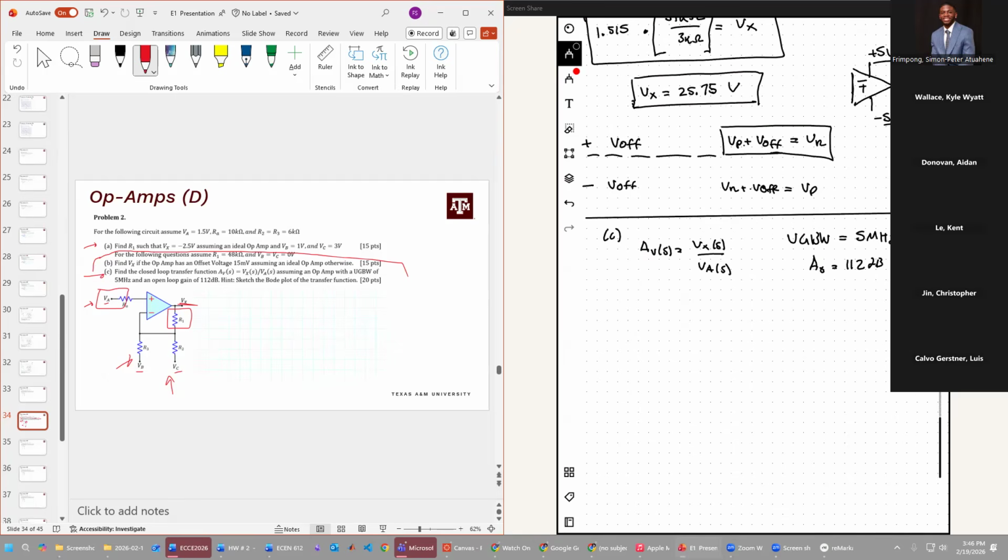All right. So, a couple of things. The unity gain bandwidth and the open loop gain are very important characteristics. And mind you, these parameters define and immediately tell us that this is a non-ideal case, right? So we no longer can assume VP is equal to VN, and we can't just assume the current flowing in is zero. Let me just say it like this, right?